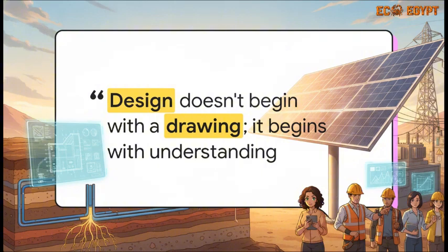I mean, if you don't actually understand the soil resistivity of your site, your grounding calculations are pretty much useless. A complex AutoCAD drawing is just a pretty picture if it's going to fail in the field. We are engineering reality here, and reality doesn't forgive bad math.